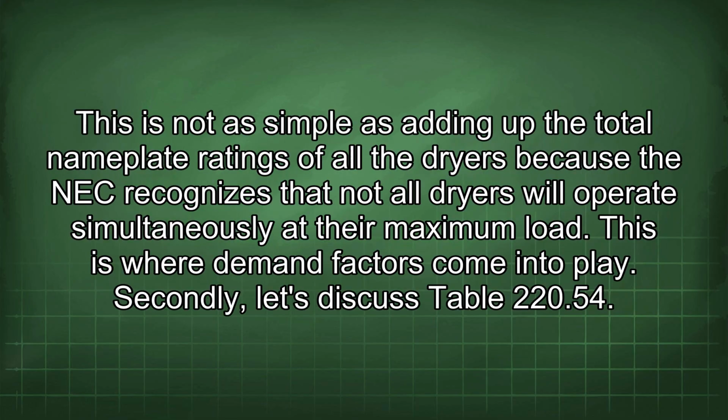This is not as simple as adding up the total nameplate ratings of all the dryers, because the NEC recognizes that not all dryers will operate simultaneously at their maximum load. This is where demand factors come into play.